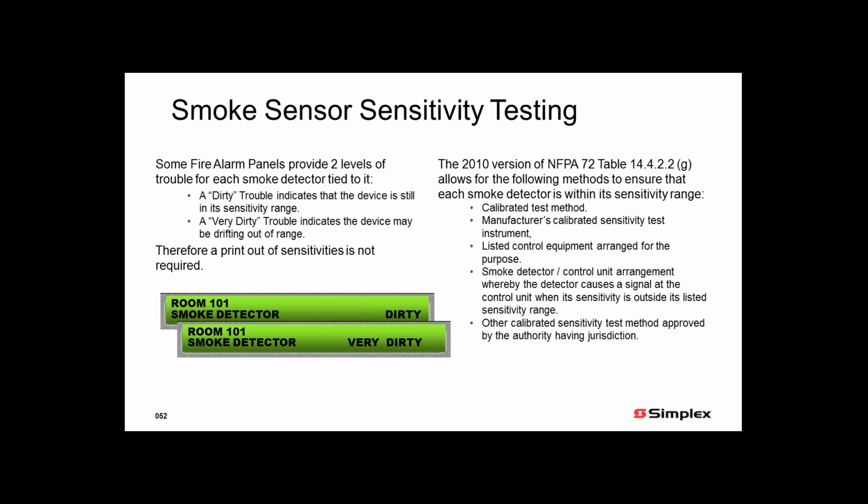The right-hand paragraph is interesting in the sense that it talks about the NFPA 72 calculations, 14422, and what that essentially says is that for a detector to pass the UL listing process, it needs to be calibrated, and we need to prove to UL that we're operating at certain temperatures, at certain thresholds, and with the sensitivity requirements. So the UL listing required to get that NFPA 72, all of our detectors meet that, and then the performance of the drift compensation helps ensure that they stay operating properly.